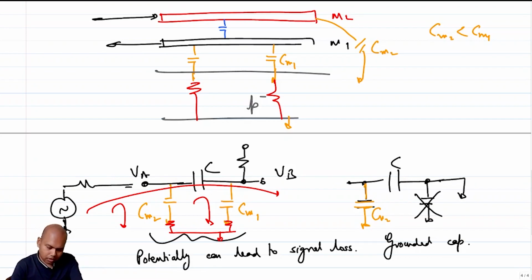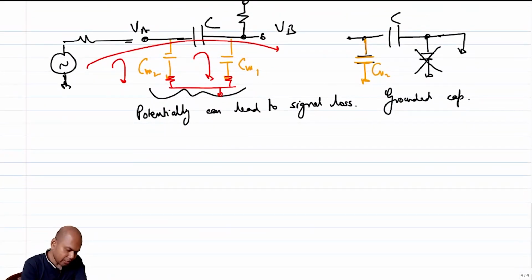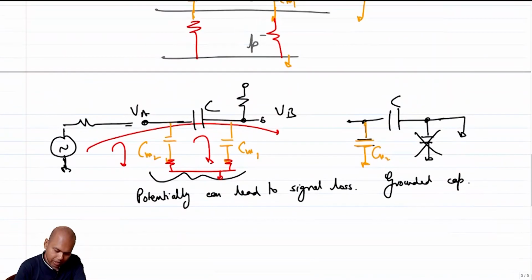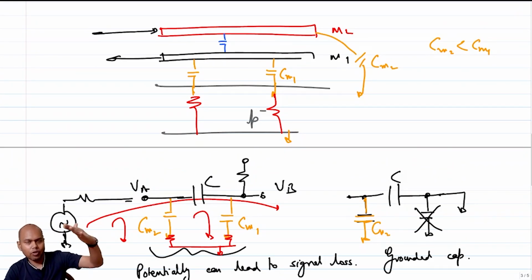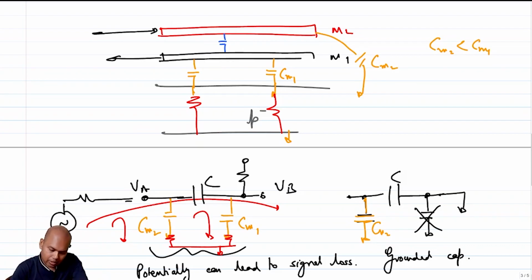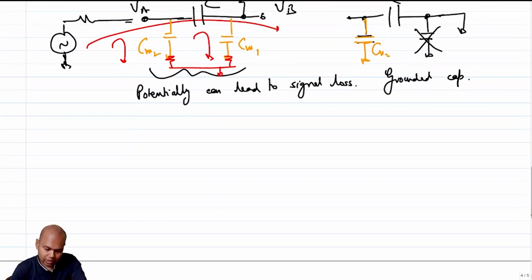Okay, so fortunately there is a solution. This type of structure is called a metal-on-metal capacitor, right? You have one metal layer, then an oxide, and on top of that, metal. But even though we are used to drawing capacitors like this, if you look at the actual metal stacks